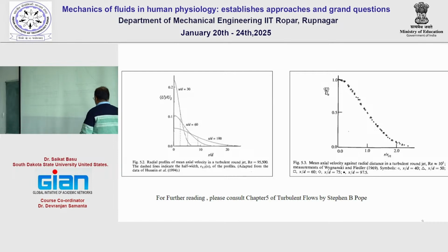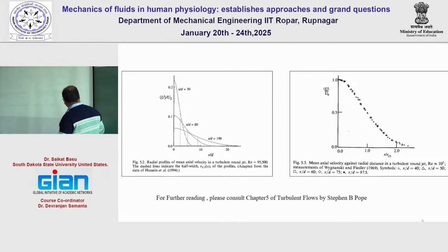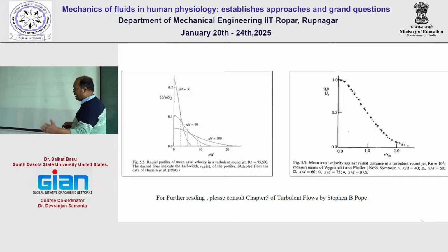And then the shape we have called jet entrainment is a self-similar behavior, just like when you studied the 2D flat plate boundary layer, we studied the Blasius similarity solution, right? In the Blasius similarity solution, we plot u by u infinity against y by delta, and then we say that at all locations, if we non-dimensionalize, the velocity profiles will match.